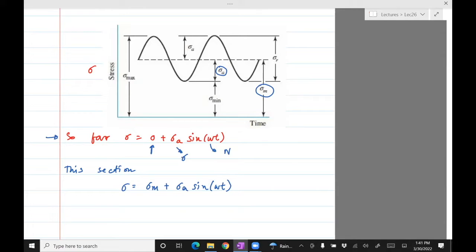For example, when you try to understand a material, when there are just two parameters to be varied, sigma A and cycles, what you do is keep the stress constant and then keep increasing the cycles n till it fails. And remember, that gave us 1 point on that SN curve. And then we do it for a different sigma and so on. Now, if we add another parameter to the mix, sigma m, we have to keep sigma m and sigma A constant, load the specimen with cycles till it fails. That will be 1 point. And then you keep repeating that multiple times.